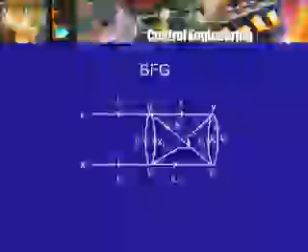Fortunately for us, there is only one forward path, and that is 1 by Kb. So, omega m is equal to the expression multiplying Ea, the denominator of that will be delta, the numerator will be this forward path gain 1 by Kb. This forward path gain will be multiplied by what remains of delta when we remove non-touching loops. Now, the only loop we have has both omega m and Ia, therefore, it touches this forward path Ea to omega m. Therefore, what remains of delta is only 1.